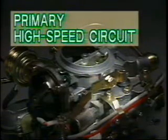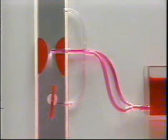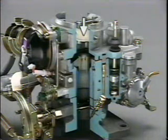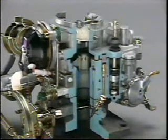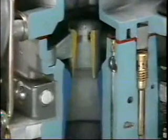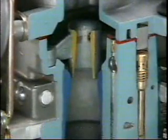Next is the primary high-speed circuit. The construction of this is similar to that in the carburetor model we looked at earlier. It is the most widely used main circuit, although there are mechanisms that activate to assist when extra power or speed is needed. This side is the primary barrel on this model. The Venturi is designed this way for maximum mixing of air and fuel.